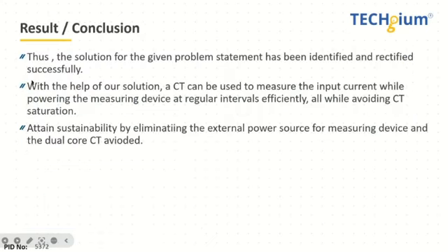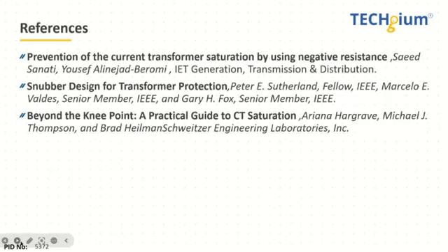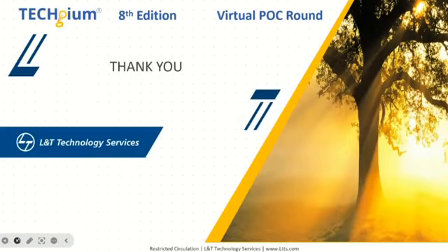And in the result, with the help of our solution, a CT can be used to measure input current while powering the measuring device efficiently while avoiding CT saturation. And these are the references we used for our project.